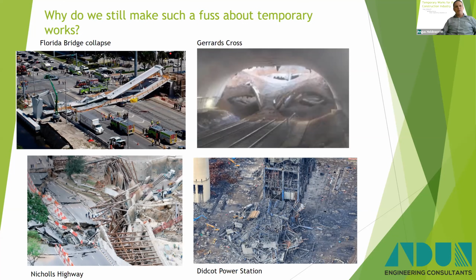There were serious signs of distress with this structure. I mean, serious signs of distress 4, 5, 6 days before this collapsed. And it's really chilling to read the report and shows how people knew there was a problem but were unwilling to act. It also shows the failings in the design, how people cut costs and therefore cut scope out of their own design works, and it wasn't checked properly. There was no consideration at all of the temporary condition, which was really quite scary, given that it's clear just by looking at it, the temporary condition was far more onerous than the permanent condition.